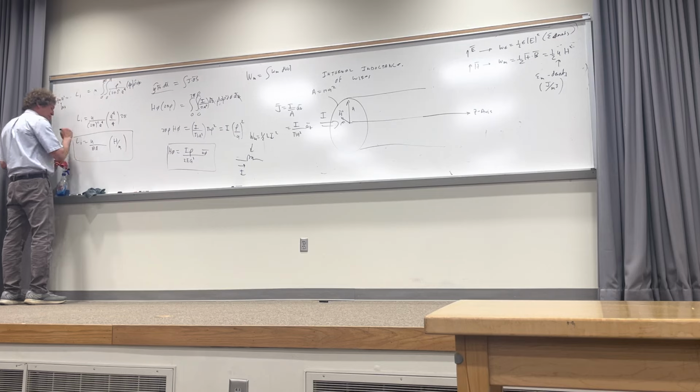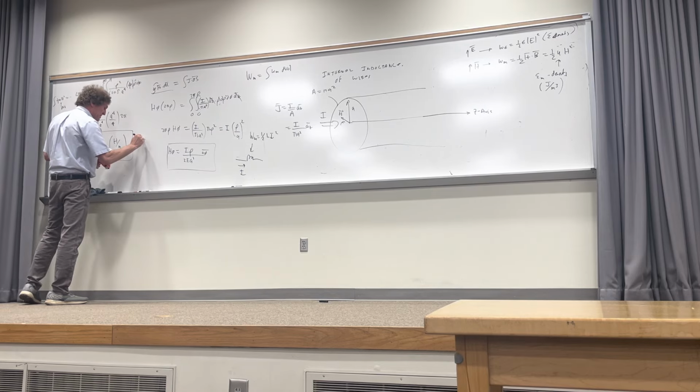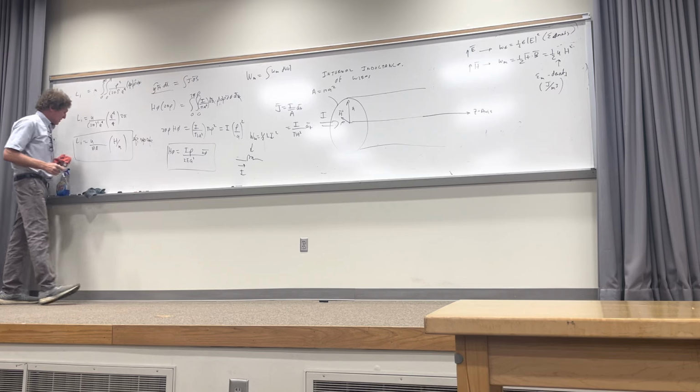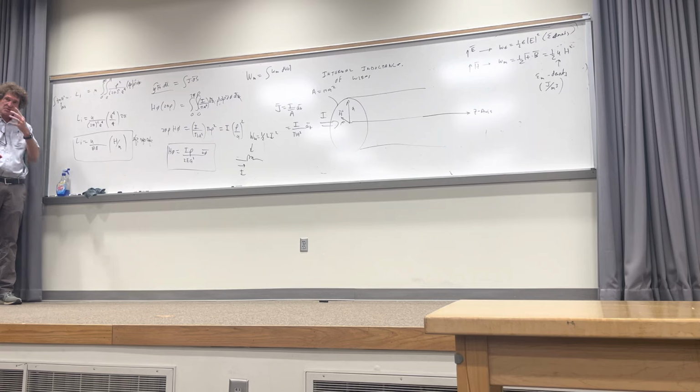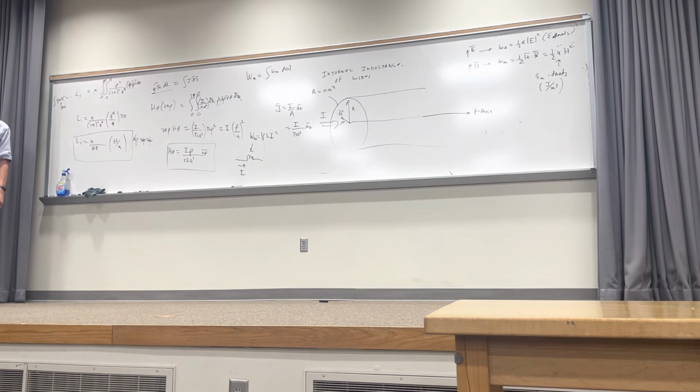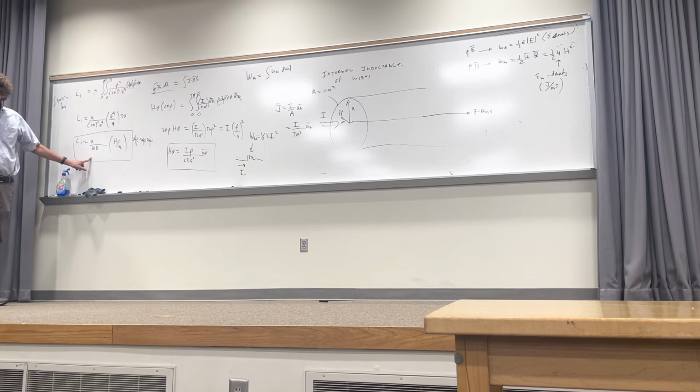This is a real important thing to take note of. I'll tell you why in a second. Now remember, that's the internal inductance of a wire. What is there one thing about this that should just jump off the board at you? Internal, does the radius of the wire make any difference? Not one bit. It doesn't matter what the radius of that wire is. The internal inductance, this is something that's internal to the wire, not external, does not change one bit. This is a small number. All right. But it is a number nonetheless.